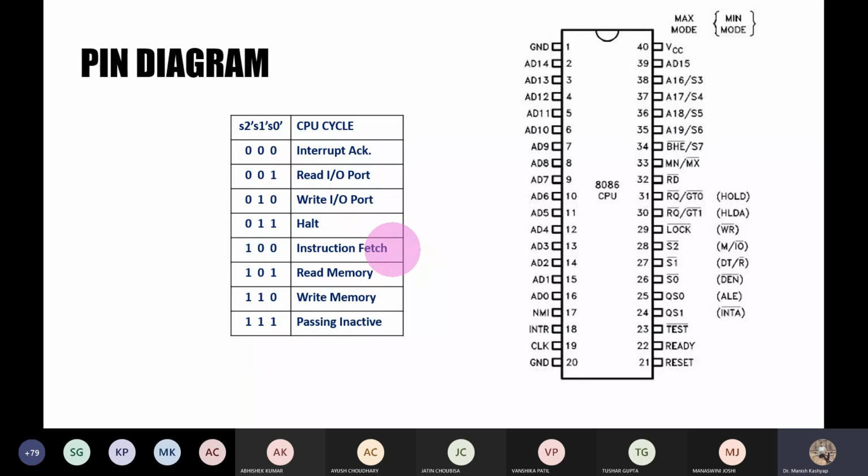So if the instruction fetch is going on, then we will know it, together with, in parallel, there might be decoding or executing. Instruction fetch happens in the case when 2 bytes of the queue are empty, not before that. So this will also indicate to us that actually 2 bytes have been emptied from the queue. So the instruction fetch operation is used there.